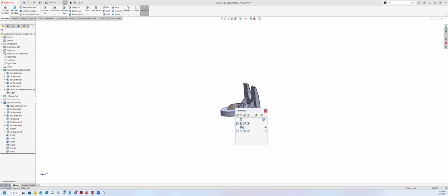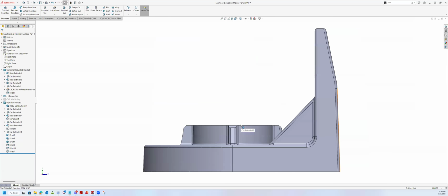Yeah, absolutely. Great point. You could be at 6 millimeters if the ribs are 3, and that may actually be a really good way of doing it too. Or 4, like you're saying, because 1/8 inch is decently thick for a good injection mold too.